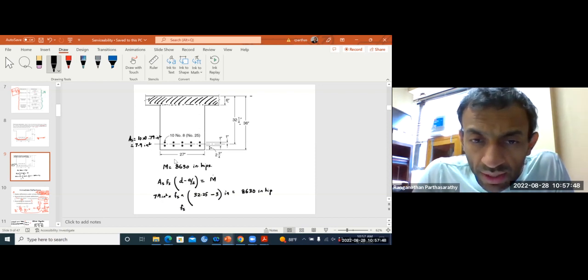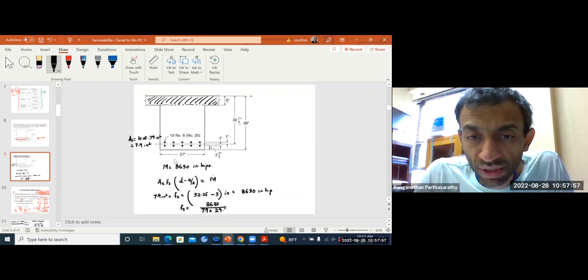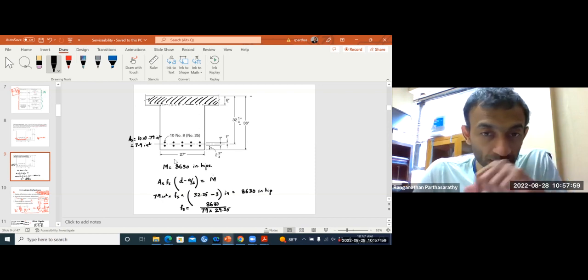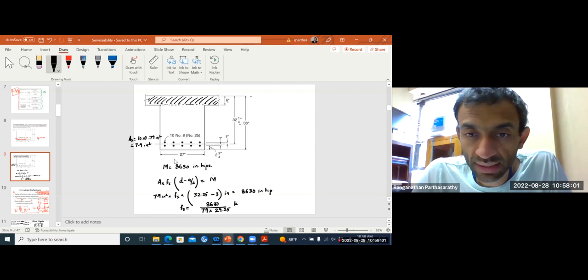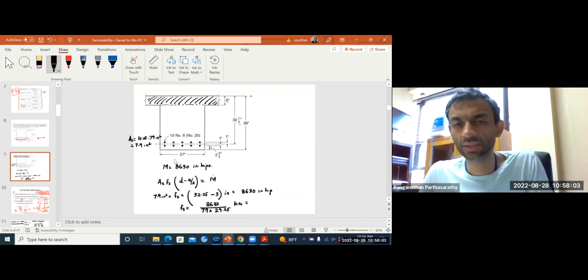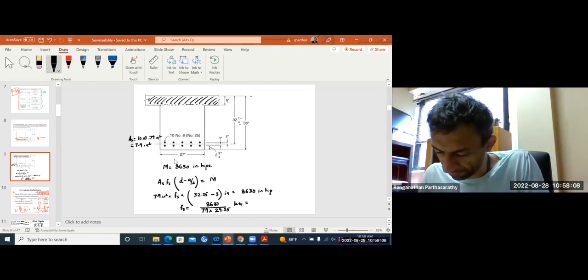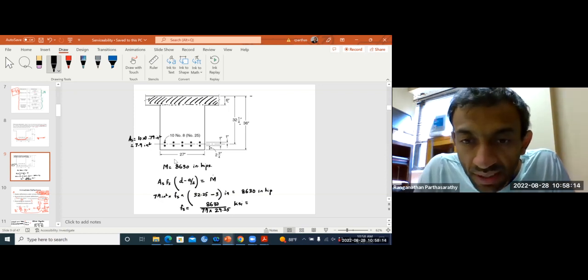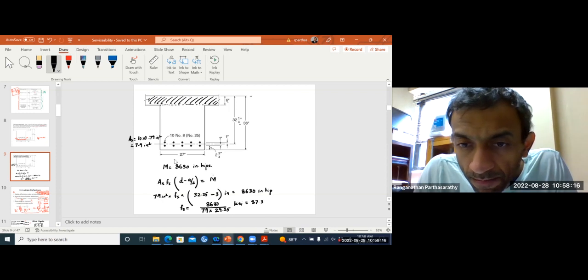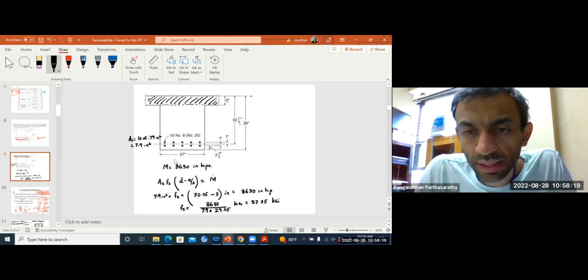So from here you can calculate Fs is 8,630 divided by 7.9 times 29.25 ksi. So that is 37.35 ksi.